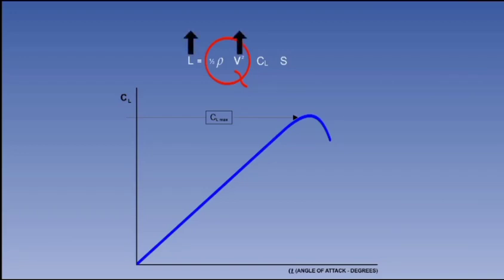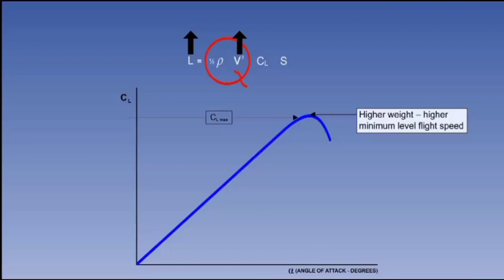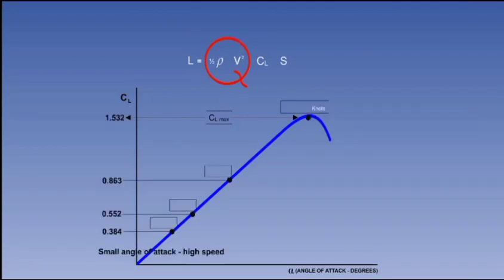The lift formula can be used to obtain the data, which can be applied to the lift curve, but this can only properly be done if the specific values to be used are converted to SI units. To calculate speeds, we need to rearrange the lift formula so that velocity equals the square root of the ratio of lift to the dynamic pressure and the wing area.